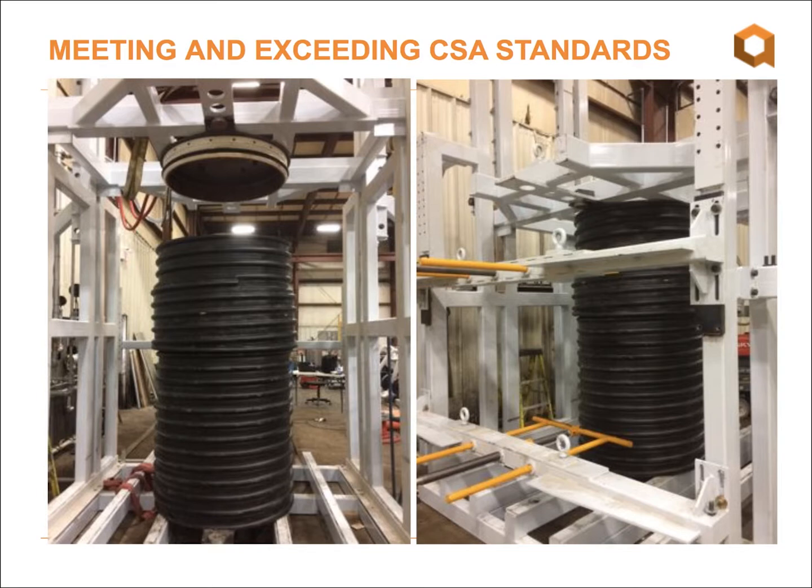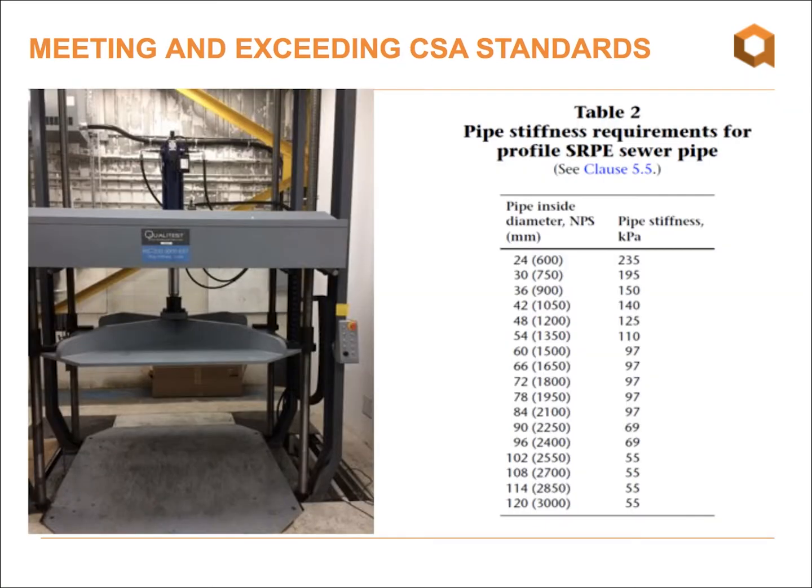And it's also very important to be able to validate the stiffness of your pipe. So we needed to acquire a machine that could actually do a stiffness test on a pipe 2100 millimeter in size. So this is a picture of the machine. What is done is you deflect the pipe to 5% and you measure the stress, and in our case, we want it to be at 320 kPa.